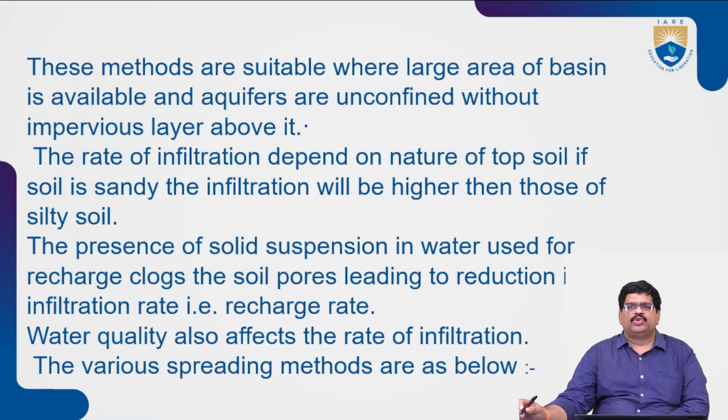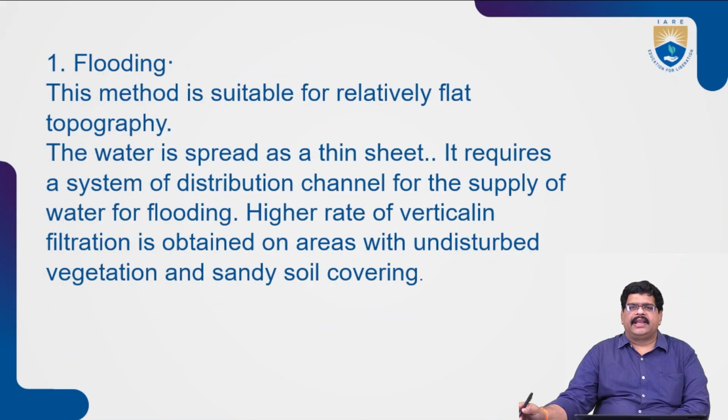These methods are suitable where basin areas and aquifers are available. The rate of infiltration on the top of the soil, such as sand, is higher than on silty soil. The next point is that suspended solids in the recharge water can reduce the infiltration rate. Water quality is therefore very important, as we discussed in the rate of infiltration. These are all direct methods.